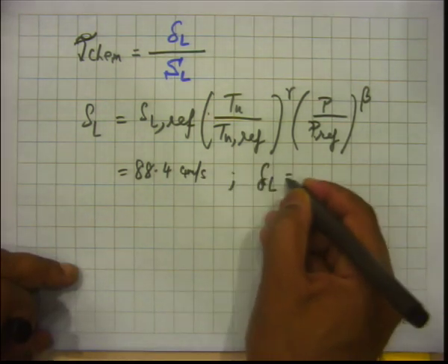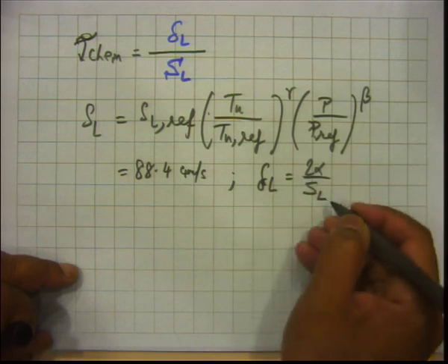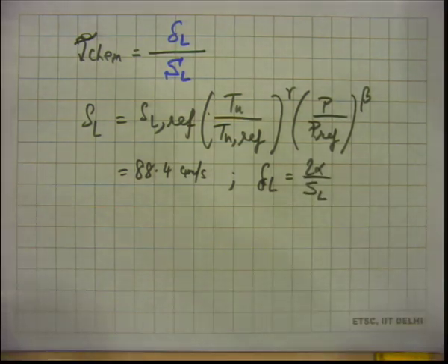We can get delta by using this. So, you have to calculate alpha, and there is some appropriate temperature he has taken in this example. Again, you can look this up. In fact, in this problem he has taken the thermal diffusivity to be half of Tu plus Tb. Okay, this is not exactly consistent with what he had done in the laminar flame calculations which we had done previously. But in this problem he has taken it to be half of Tu plus Tb. Alright, we are not placing so much importance on very accurate values. So, he estimates thermal diffusivity at half of Tb plus Tu.